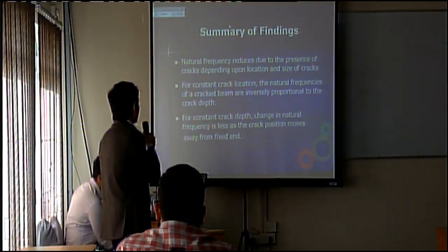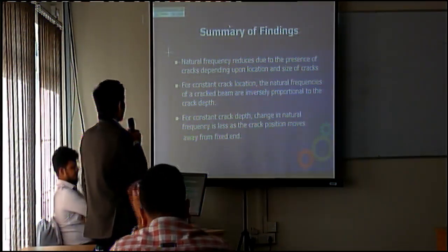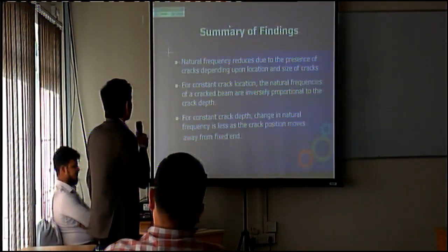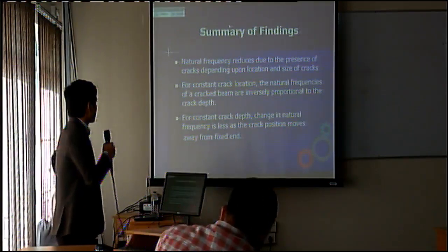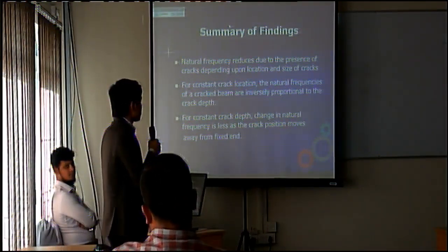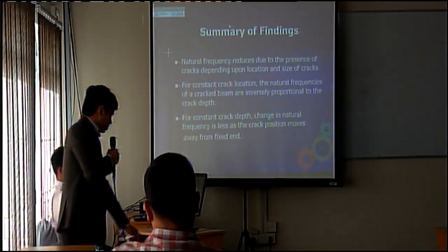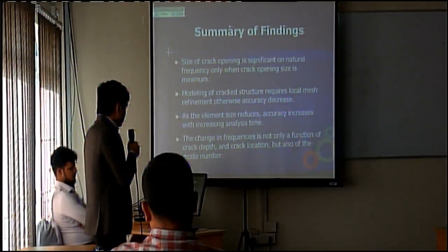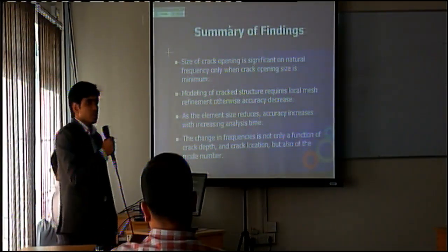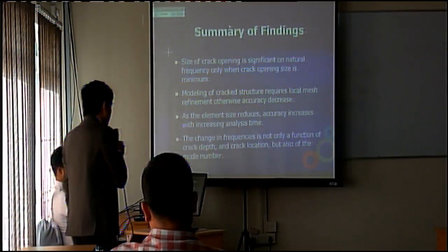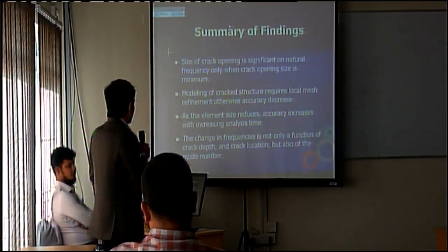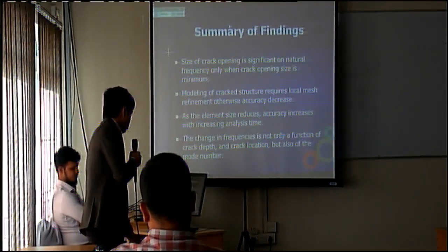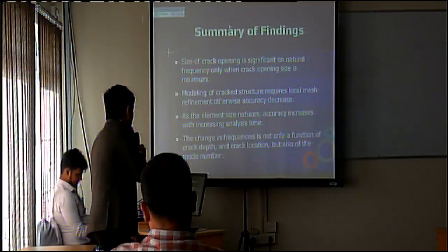These are the findings: natural frequency reduces due to the presence of a crack, depending on the location and size of the crack. For constant crack location, the natural frequency of the cracked beam is inversely proportional to the crack depth, and for constant crack depth, the change in natural frequency is less as the crack position moves from the fixed end. The effect of crack opening size on the natural frequency is significant only when the crack opening size is minimum, and the modeling of a crack requires local meshing, as I said earlier. As the element size reduces, the accuracy increases with increasing analysis time. It also depends on mode shape.